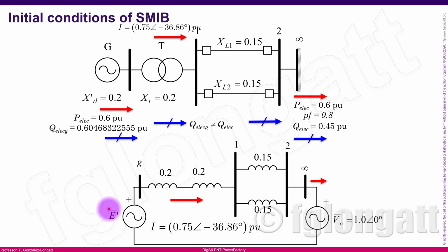In this case, we are using the voltage behind the reactance, and that is the simplest model that you can find. Okay, if you are using the 7th order model or any model as complex as the one typically used inside PowerFactory, of course you will have more state variables that you need to know. Well, the job now is to calculate this internal voltage. The reason that we need to know this internal voltage is that inside it we have one of the state variables. If you remember the most basic equation that we used to describe the dynamics of the electrical power system considering a synchronous generator, the most basic model is the swing equation, and the swing equation is a second order differential equation in terms of delta, the rotor angle, okay?